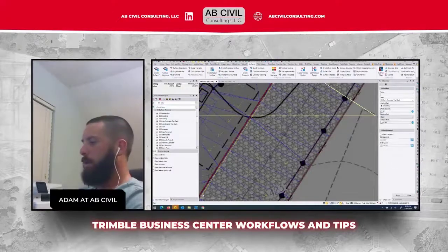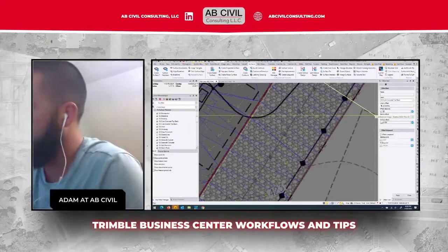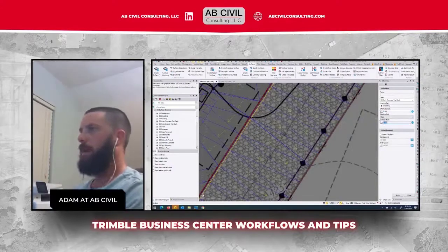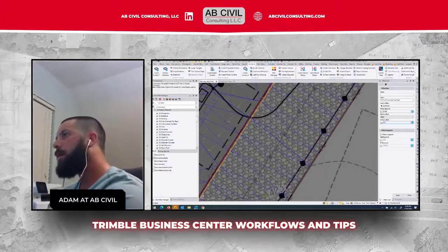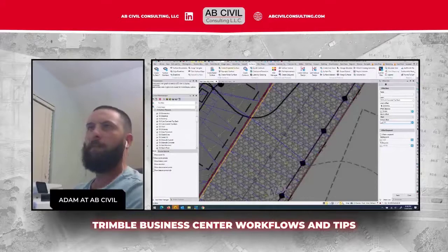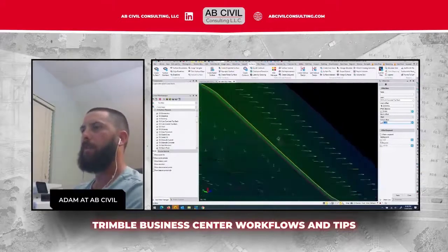And this one, let's do an 8-foot sidewalk, offset to the right. Then vertical, we'll do 0.12, which is 1.5%. So it's going to offset at 0.12 to the right. I'll go back to plan view or 3D view.